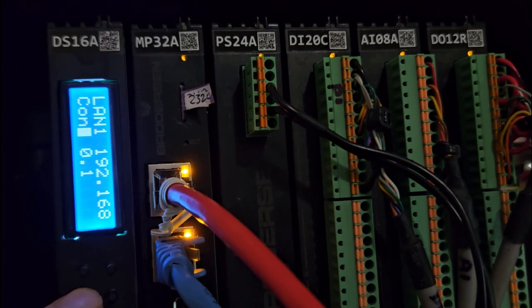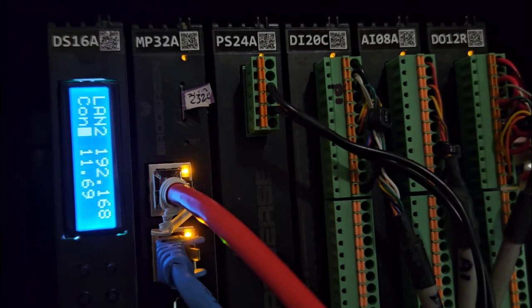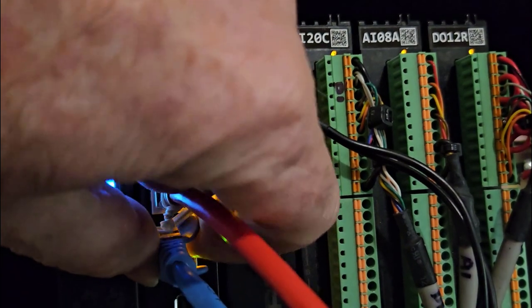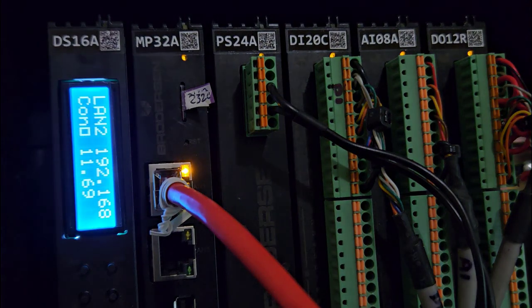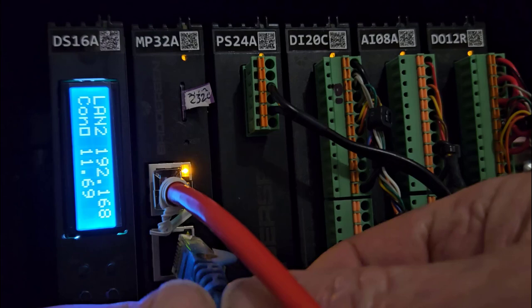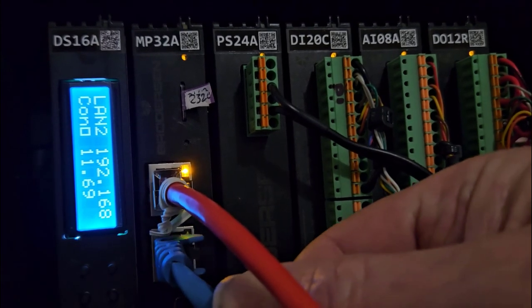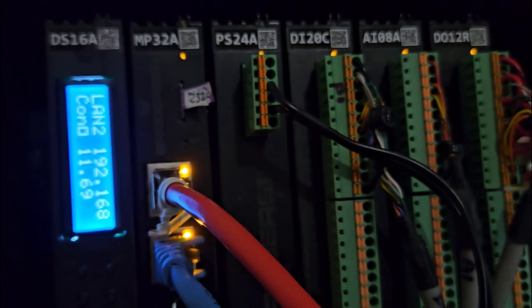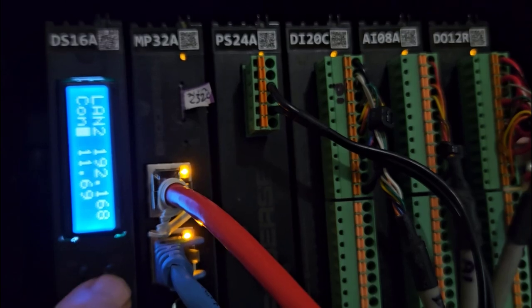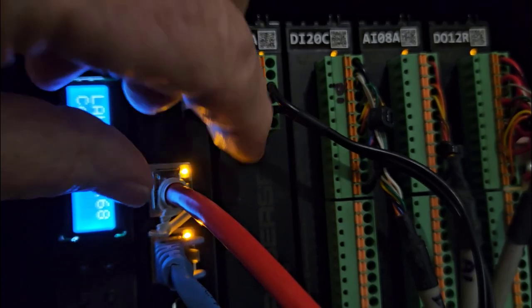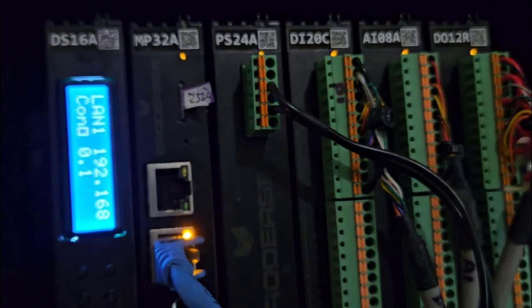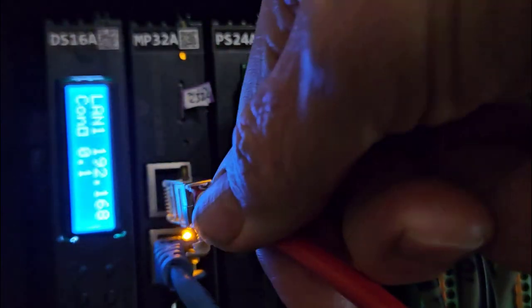And here's an example of showing the IP address LAN 1 and IP address of LAN 2. If I take out the cable for LAN 2, you see that that little connection block changes. Plug it back in again, the RTU is going to detect that it's present, and we'll just change back to LAN 1 and prove we've got the same trick happening on LAN 1.